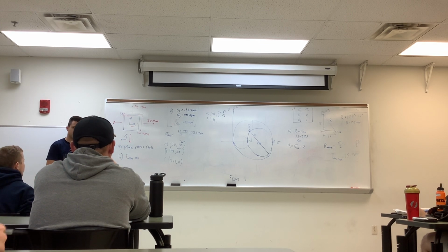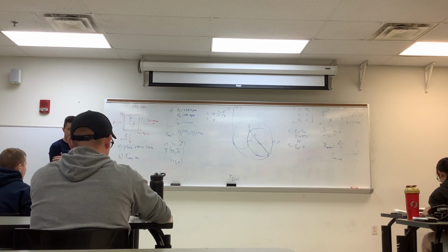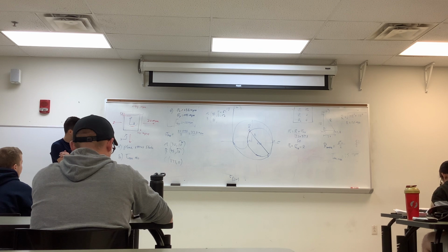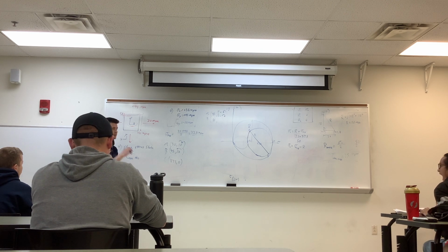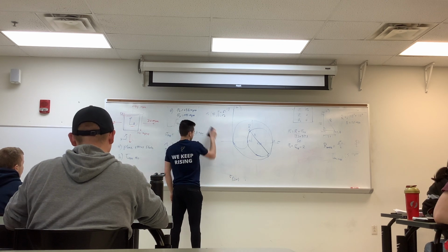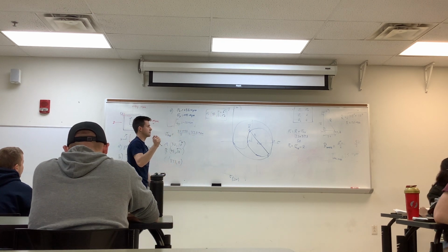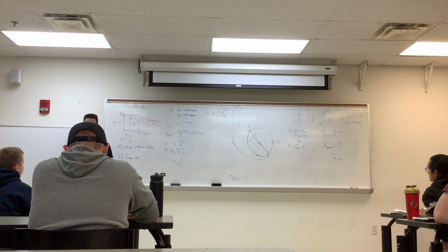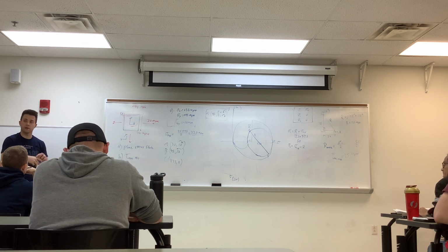Anything else with this one? And for the coordinates, to determine whether the shear in the coordinates is positive or negative, it's kind of like this. If the shear is positive, point A will be counterclockwise. If it's negative, it'll be clockwise, and then the opposite for point B.